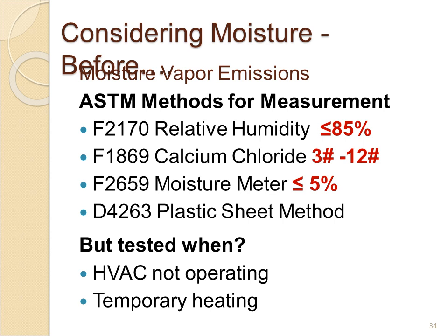The numbers that you see on the right-hand side are relatively safe numbers depending on the type of products you use. Most products that you're going to use in your assembly, be it levelers, membranes, grouts, mortars, if you're less than or equal to 85% RH, it's typically not a problem.